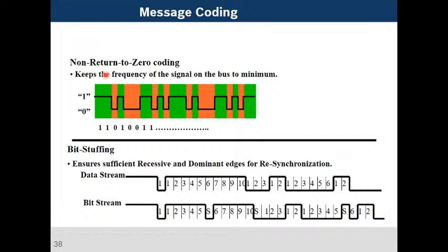It's not completely used for other protocols, but it's used in CAN, and even in some other protocols. If you imagine how data will be transmitted: start of the frame, 10 bits of identifiers, control bits, data bits, and the data byte. If you transmit one dominant bit and then 10 recessive bits, 1 1 1 1 1, that's almost 7FF, and then this will not be the same on the bus.